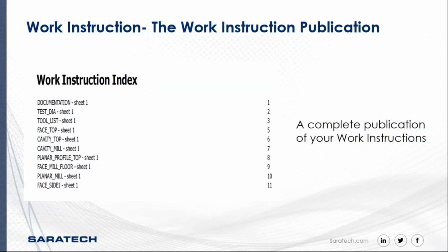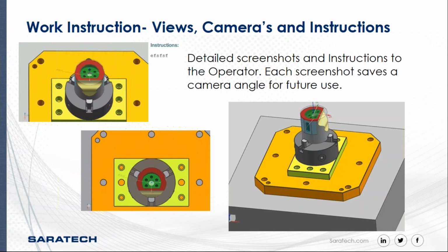When you develop these work instructions and you choose to do a screenshot, that screenshot will create a camera view in your operation tree so that you can go back and see what you did in that camera view. You can see that in this camera view here, this is the actual demonstration that I'm going to be doing for you shortly.